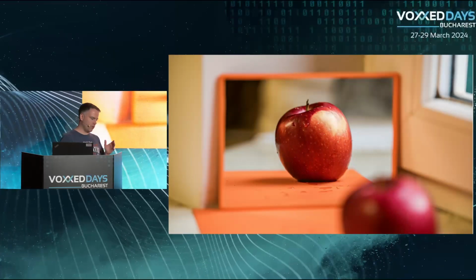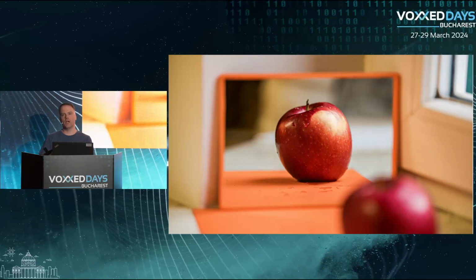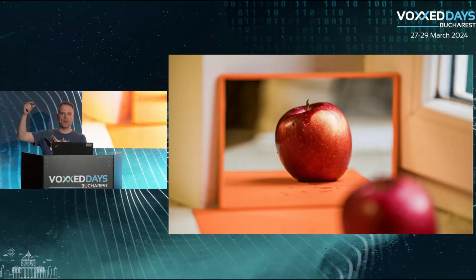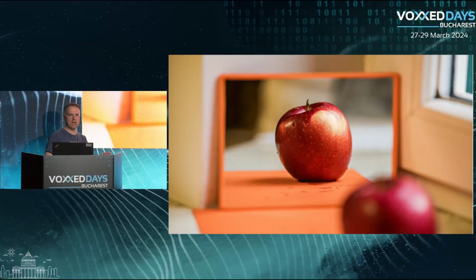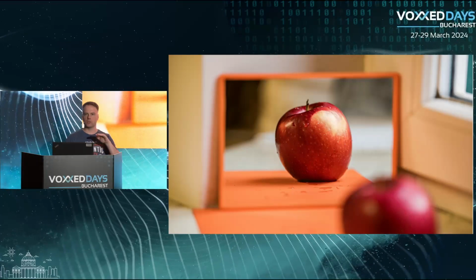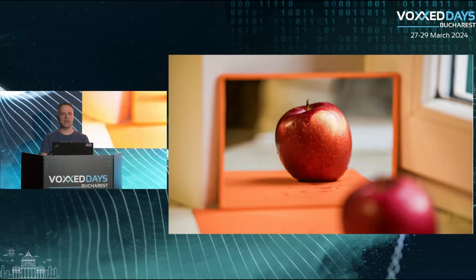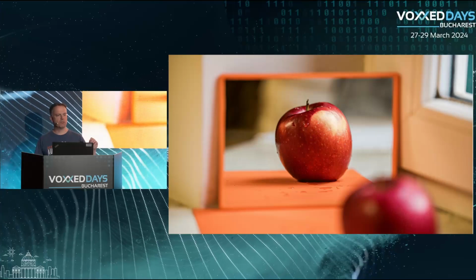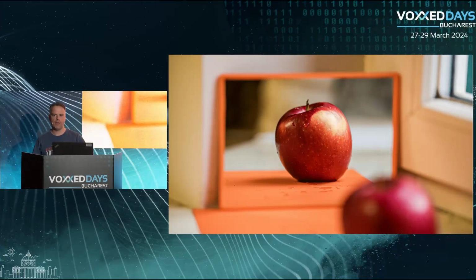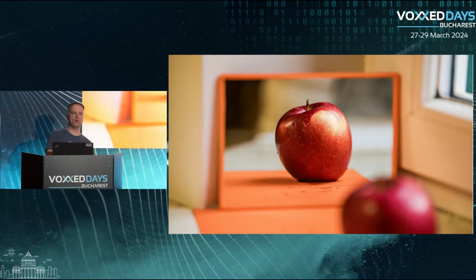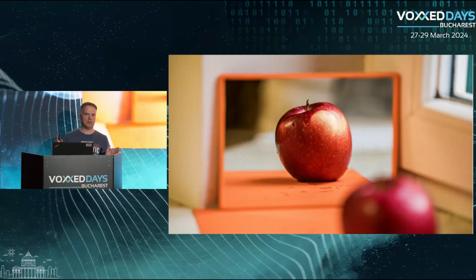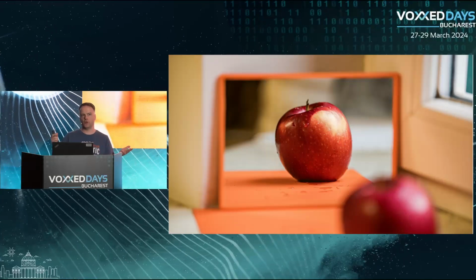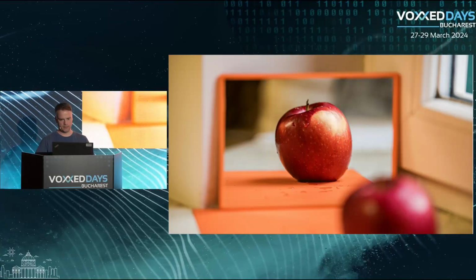And within that, so we have that plasma emitting EUV light. We somehow need to get that EUV light on top of that resist. And for that, mirrors are used, but it's not like the mirrors you have at home. This is a mirror that has about 100 layers of special coating. And if you would extend it to the size of Germany, the biggest bump is 1 millimeter. It's super flat, so that most of the EUV light will end up on top of the wafer. Because EUV light, it quickly disappears. So everything that's in its way, make sure it disappears, and we don't want that.